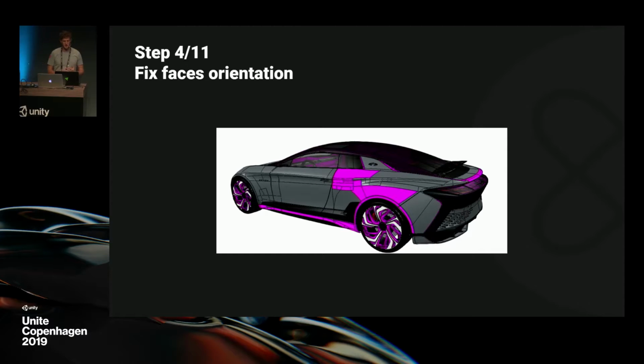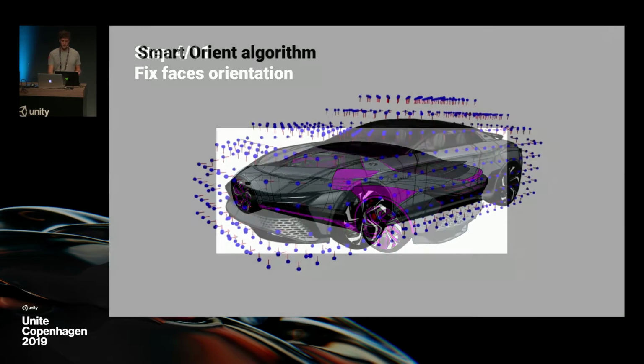And as Cédric said, the repair mesh function sets orientation per propagation, but some incoherencies remain here. It's due to the fact that we have only surfacing patches, which are very, very hard to orient. So for these cases, and for these surfaces we see here, what defines which face orientation is correct will mainly depend on the user's point of view. So here we'll use another algorithm we call Smart Orient. This function will properly orient all polygons in the same direction automatically according to external points of view.